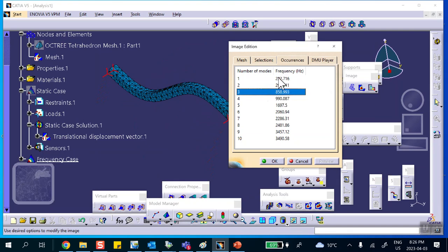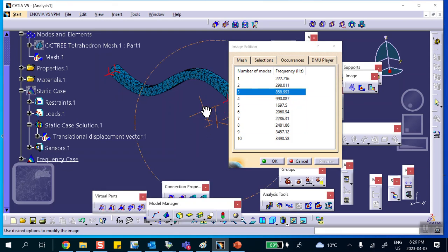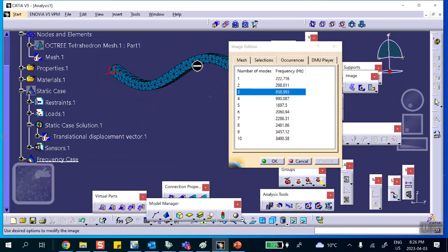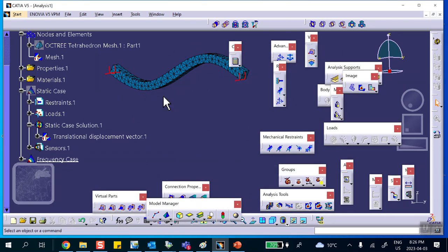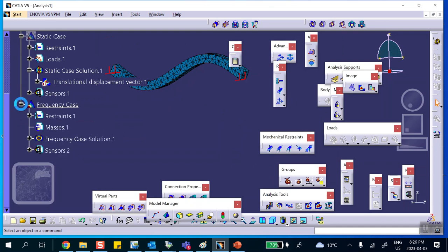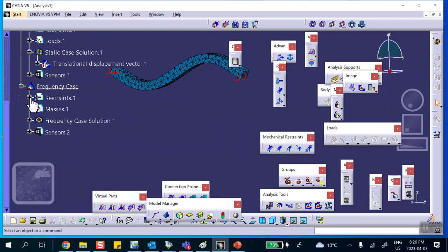So you know what, we're not going to pay attention. These are important. Like this one, for example, is bending. So we're going to say use all 10 of them. If you put your loads so that it doesn't excite those, then it doesn't matter. So we're going to use these default 10 frequencies. Some of them are useful, some of them are not going to come into the picture because the direction that you're applying the load will not actually excite those particular modes.